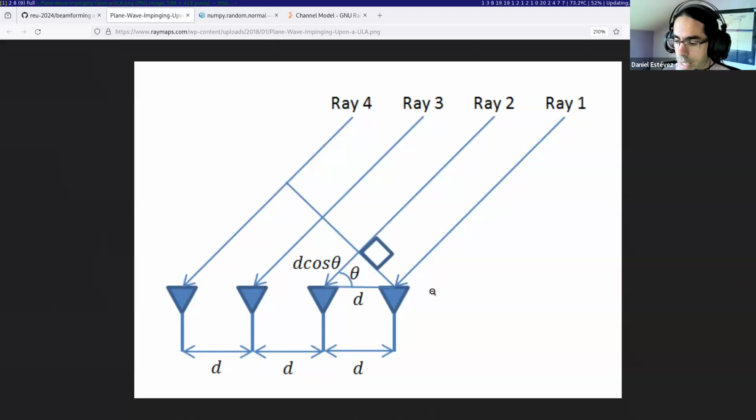That means that depending on the frequency, the beam width of the signal might be a fraction of a degree, let's say a quarter of a degree, for example. And then when we point these dishes at the sky, anything which is in that area of 1/4 of a degree around the position where we are pointing the dishes gets into the antenna because of how the antenna beam is.